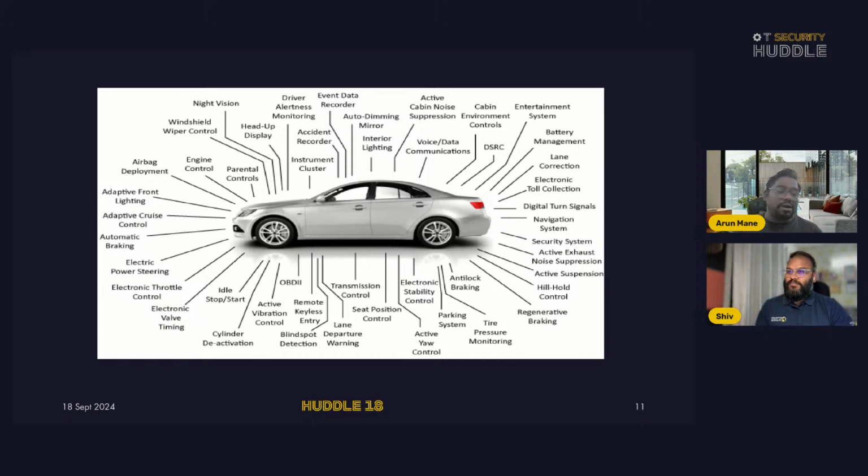Depending on the feature, the scope would be at the vehicle level. So these aspects come into the picture, and these are the threat maps. If you go for TARA on the vehicle level, they will see these features as assets, and based on those assets they derive the risk, calculate the risk and the impact analysis, and based on that come up with a cybersecurity concept and requirements. The entire TARA report goes to the testing and validation program, the cybersecurity testing, to a penetration tester, and the cycle goes on. The pen tester comes up with vulnerabilities or new vulnerabilities, which can get added to the TARA itself, and it matures while testing goes on. So these are the things we need to consider.